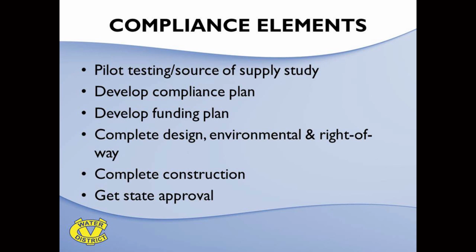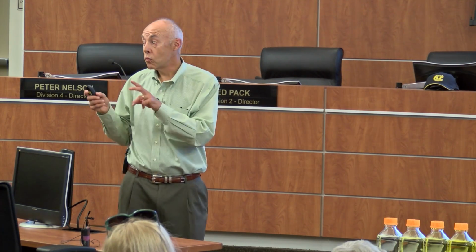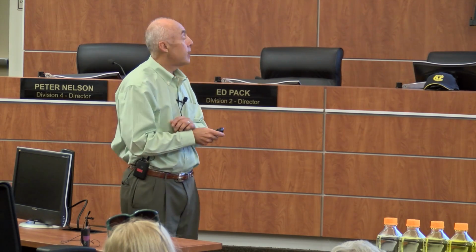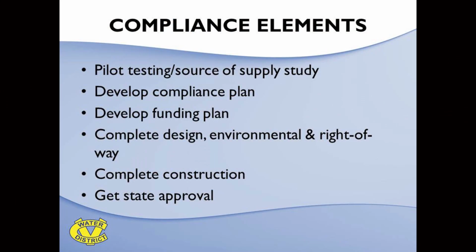I'm going to try to get into the essence of how do we comply with this new regulation by building water treatment facilities. The first bullet there is pilot testing, and Steve has been one of the premier researchers of chromium treatment studies in the United States, and we have 2 studies going on right now. And that information is going to be utilized to help us decide what is the best type of treatment to use for chromium removal.